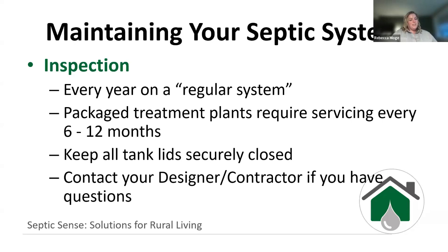So, maintaining your septic system and inspection. This isn't like a safety codes officer coming to do a site inspection. This is a maintenance inspection. So it's something that gets serviced, again, cleaning out the filter, making sure the lids are secured. And some contractors have this as part of a package. If you're working with one, they come out and provide the maintenance for a certain period of time. And again, that should be recorded so you have a record of it.